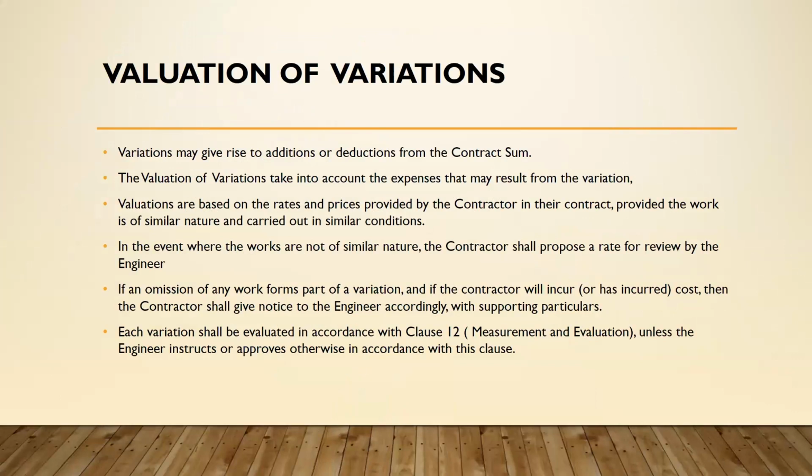Now, we cannot talk about variation without mentioning valuation of variations. Variations may give rise to additions and deductions from the contract sum.